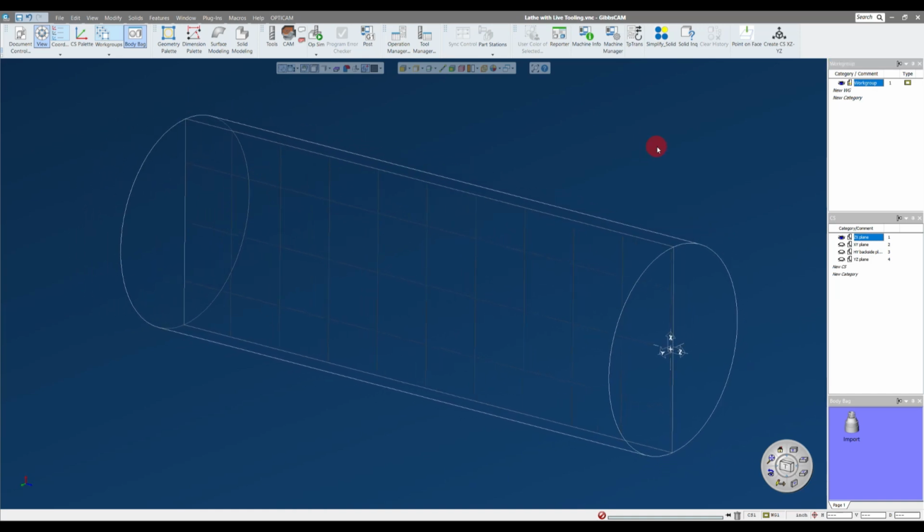So the coordinate system configuration we have for the C-axis horizontal lathe is we have our ZX plane. That's coordinate system 1 here. So this is, in general, your turning coordinate system that you're going to be using for all the turning operations on this part. You have your XY coordinate system, and that's really what we're going to be using for the live tooling operations or any live milling that we're going to be performing on the face of the model. This XY backside, we're not going to be using that for this exercise.